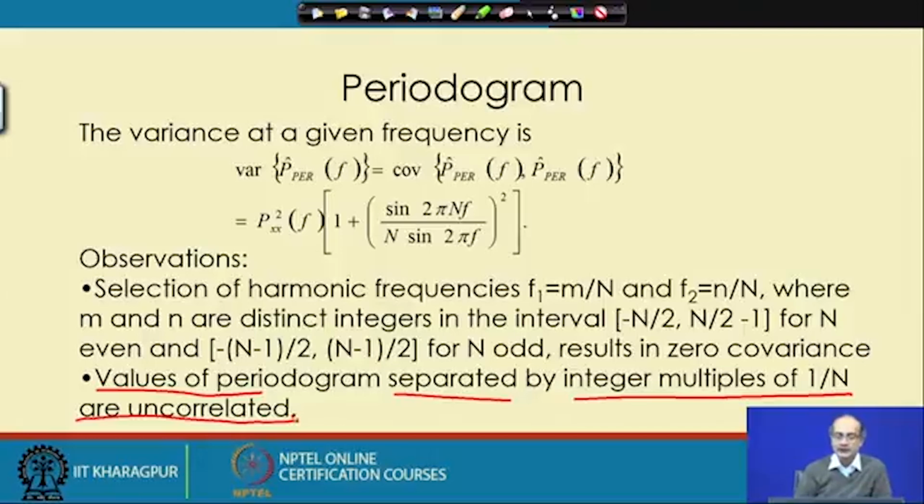Now, you get why we would expect a random noise kind of pattern instead of a constant value of the signal energy for the PSD when we take the Fourier transform of white noise and look at the absolute value of the Fourier transform.